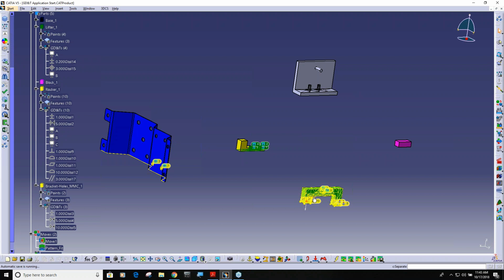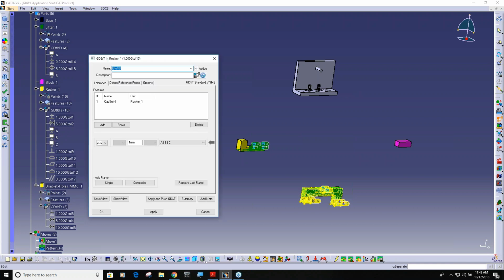Do you want me to do it? Another thing I wanted to point out too, the difference between how a CAD system creates or requires you to define a feature control frame, whereas Gary showed us that you can go ahead and define your datums and then have a profile, let's say a perpendicularity on datum B. I'm sorry, the perpendicularity is the refinement? Yeah, perpendicularity should be a refinement to profile. Okay.